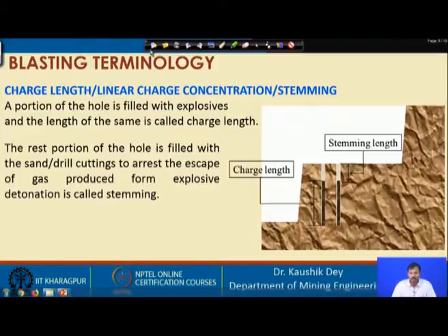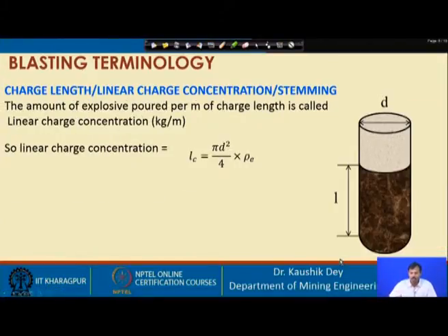Linear charge concentration is the term we use, which basically shows the length of charging of the hole, or the length of placing the explosive inside the hole. It is the amount of explosive poured per meter of charge length.